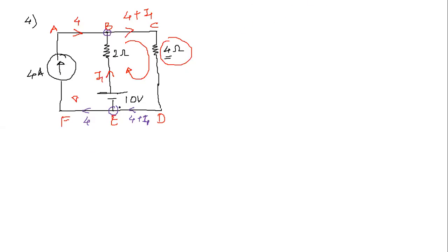So this is how in every circuit you can apply KCL. If you have a doubt whether you made a mistake or not, you can always cross-check with another junction, right? Whatever is going out should come in, right? That is how the circuit gets completed.